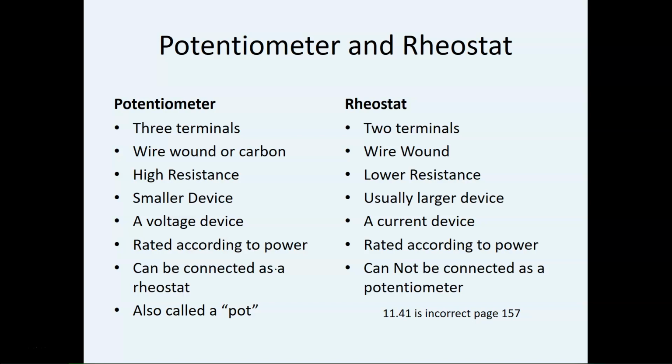They're both rated according to power, just like anything in resistance. They are always rated not just by their resistance, but by their power. All resistors are rated by resistance and power. Make sure y'all know that. It's a very big question. It's one that I frequently will ask on tests. Just kind of a heads up on that, guys. So make sure you know that all resistors are rated on their resistance and on their power.